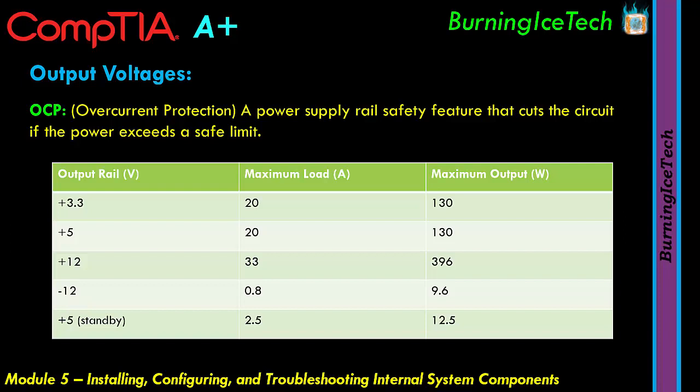You do not want to exceed a certain wattage on that rail. Each rail supports a certain amount of amps and a certain amount of wattage. So if you suspect you might have gone over the limit, or you're near the limit for one rail, you preferably want to use a different rail for the new device you want to install, even though you might still have some connectors open on the previous rail.